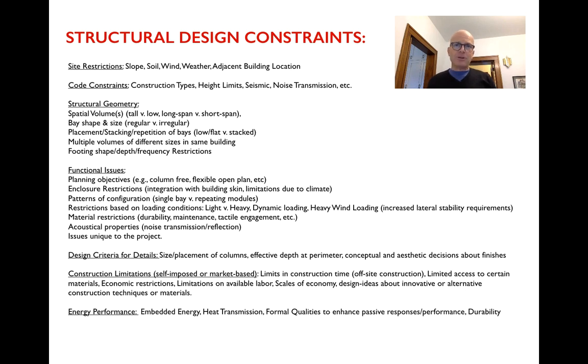And then finally, we'll also be looking at how all of this resolves itself in the ground. If we're using a really heavy structure, then we might be surcharging the soil with more weight than it can really bear, and we might have to look at other systems. If we're, on the other hand, doing something that's really lightweight, we may have more freedom in where we put the footings, how many footings we put down, and how we collect the loads before they go into the ground.